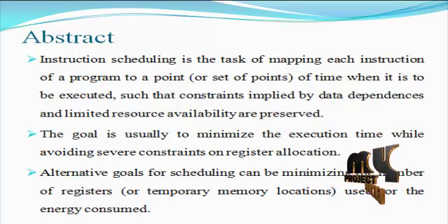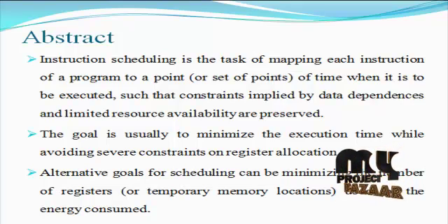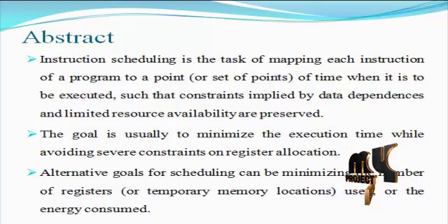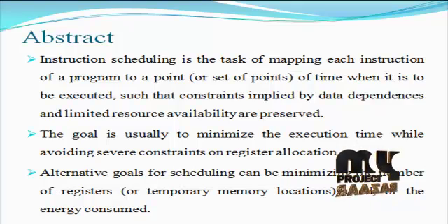The growing energy consumption leads to an increase in chip temperature, which brings an exponential growth in leakage current and consequently leakage energy. However, there are few studies of VLIW architecture. In this paper, a leakage and temperature aware design flow is presented to assist the leakage compiling of instruction level VLIW scheduling, and two scheduling algorithms are proposed for the design flow.